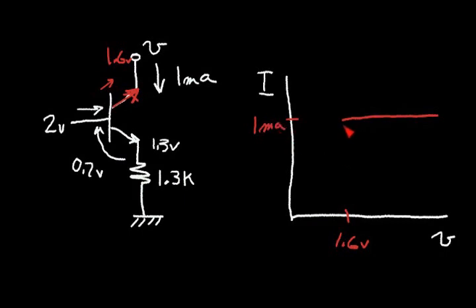Maybe my base voltage is not a perfect 2 volts, so that may vary up and down, and that'll change my current. There's a temperature dependence on this base emitter voltage. At high temperature, the base emitter voltage will shrink a little bit. Perhaps my resistor at higher temperature will increase a little bit. So there's some variation that's unavoidable. It won't be a perfect milliamp. And I cannot really operate in this region here because I would forward bias this base to collector junction diode.